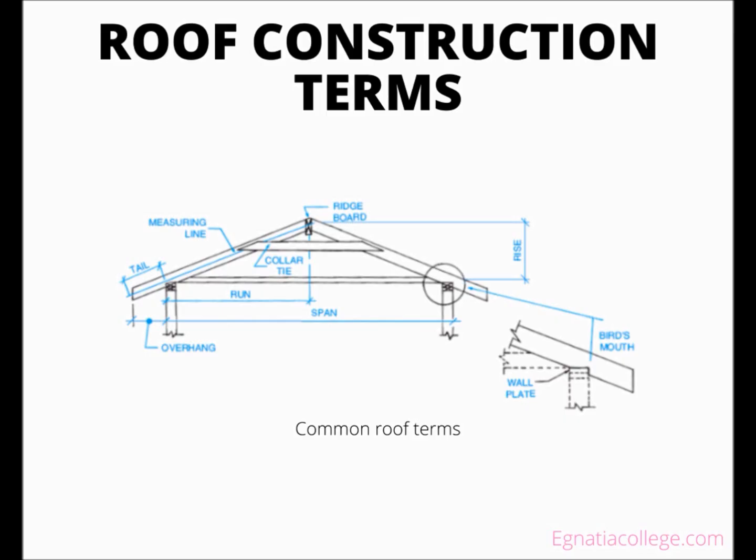Roof color matters. Lighter color roofs generally reflect more of the sun's energy than do darker colored roofs. Also, smooth metal reflects more than does the rough surface of composition shingles. By reducing the amount of the sun's heat that is absorbed by the roof covering, the air conditioning load of the building can be reduced.